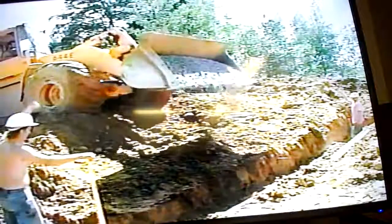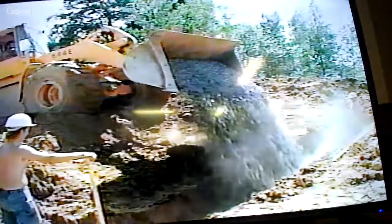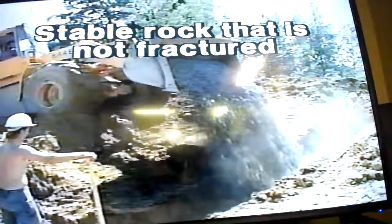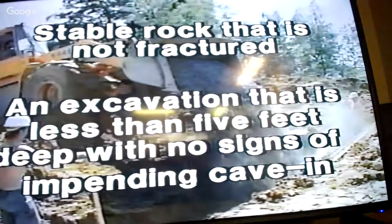There are 2 instances, however, when a protective system is not required. The first is an excavation made in stable rock that is not fractured. The second is an excavation that is less than 5 feet deep. This site must be inspected by the competent person, and the determination made that there is no indication that a possible cave-in will occur.